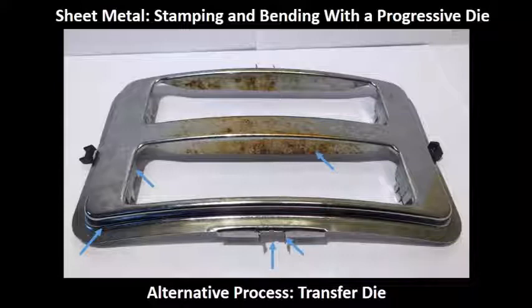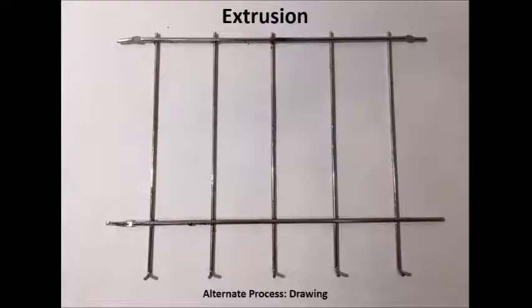Due to the complexity of the bending, there is a chance that a transfer die process was used to manufacture the lid. However, a progressive die is the most efficient method due to its higher production rate. Next, we will talk about the grill, which was manufactured using a series of processes.